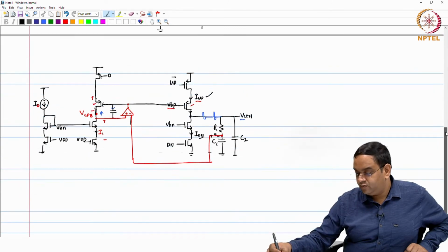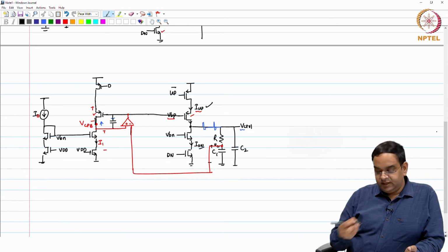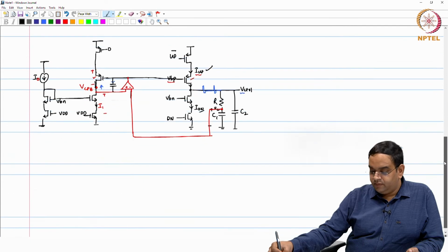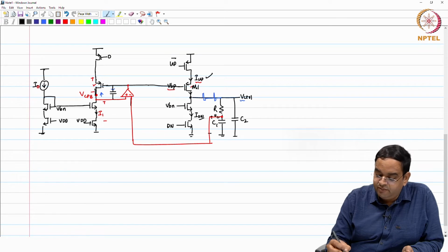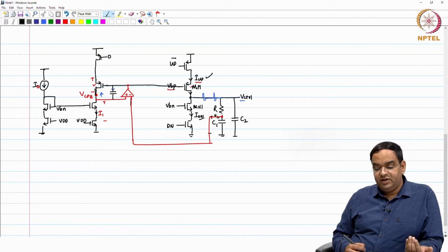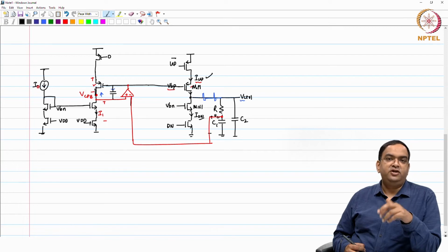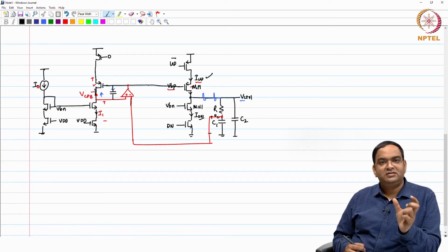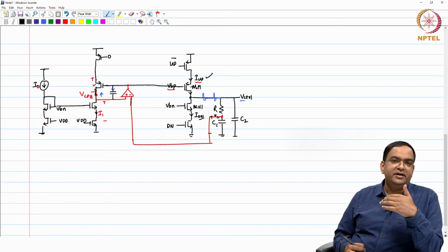Now, even after doing all these things, this works pretty well, but if you look at it, these two transistors, MP1 and MN1, go into cutoff and then go to saturation. Whenever you have a current source which is in cutoff and then during the transient goes into saturation, there is some time lag, and it is not only the simple time lag: the current changes from 0 to the final value non-linearly.